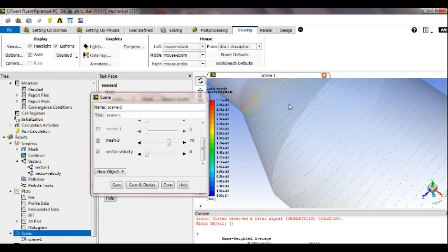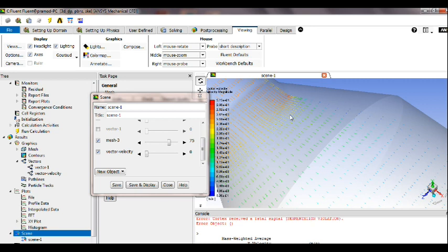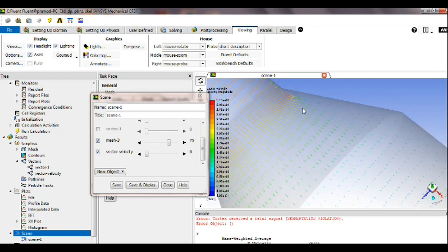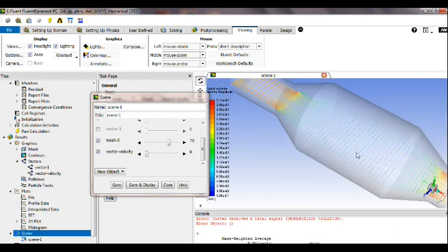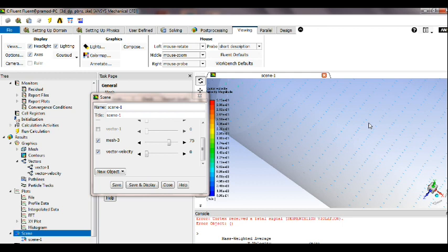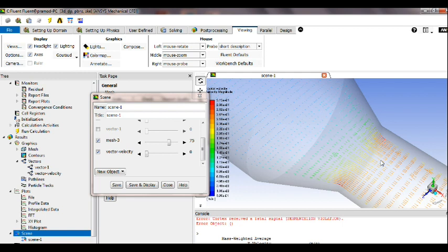The flow pattern shows that the flow enters the catalytic converter as a jet with recirculation on either side of the jet. There is a little bit of recirculation, and it passes through the porous substrate, and the velocity decreases, and a more uniform velocity distribution you can see in porous media. So this is our laminar flow actually, and again at outlet we have the turbulent flow.